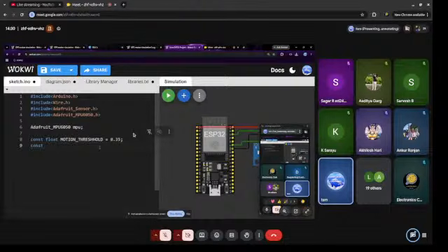Okay, I'll start again. I will explain the motion threshold value. What is the motion threshold? We have to create some threshold value. If the total magnitude of the acceleration is below the threshold value, we don't give a command to change the coordinates, because that can be any noise also. Due to some noise also, the value can change.